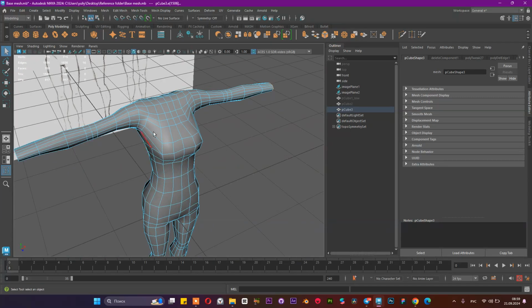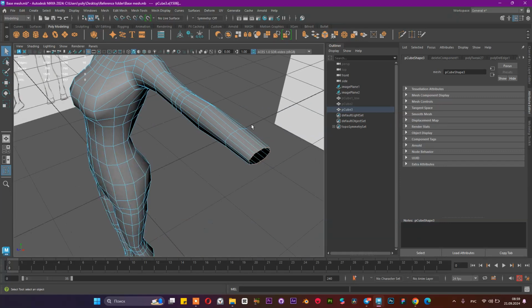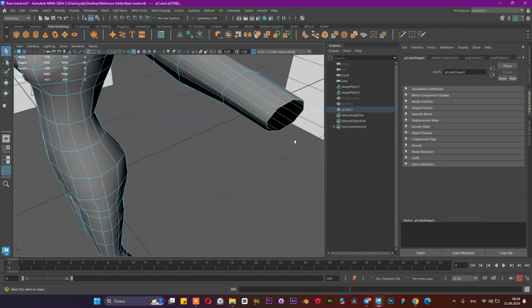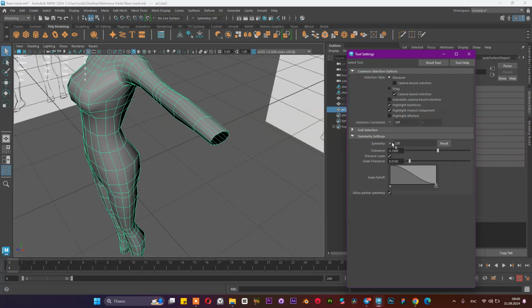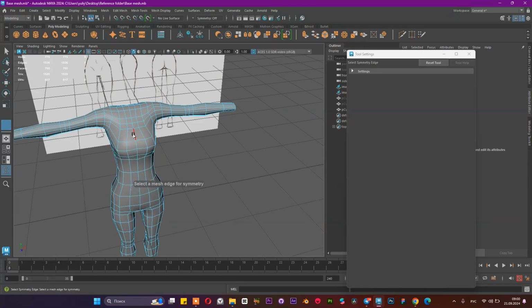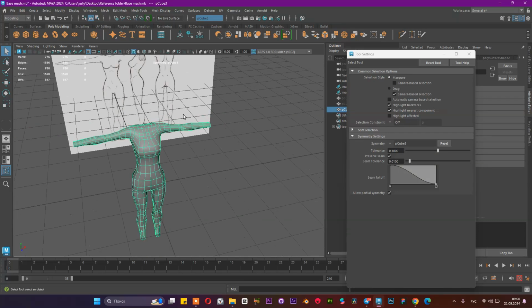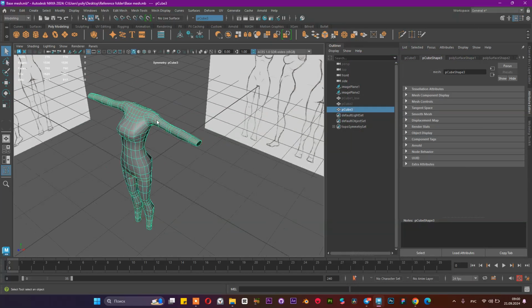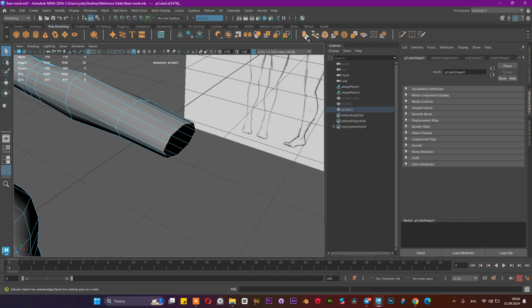For the extrude, we can select edges, we can select faces, but we can't select vertices for extrude. For example, previously we worked on the faces, now we are going to work on the edges and extrude them. But also don't forget about our symmetry settings, and if it sometimes switch off, reselect this symmetry according to the topology and the central edge. And now we can continue work with our character. And extrude these hands.